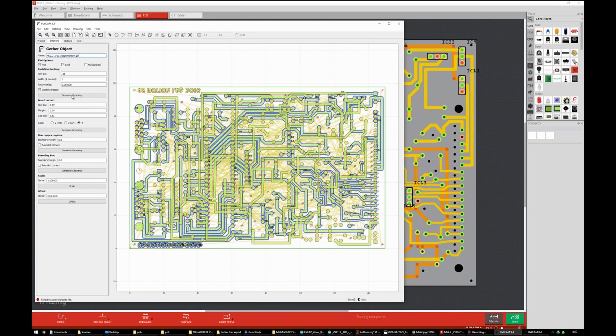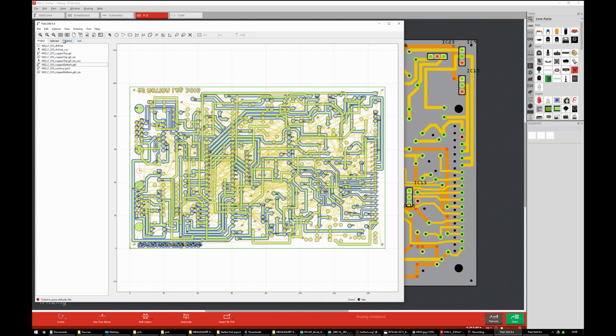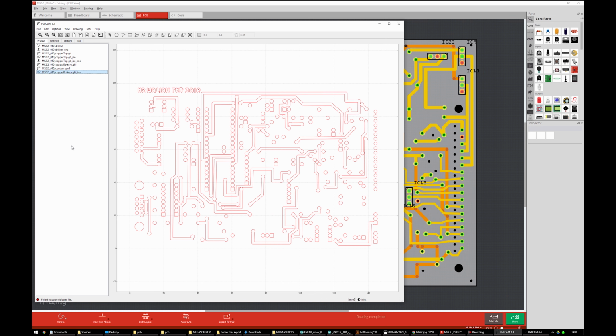Now in theory, all our tracks should be nicely separated. I'm just going to verify that by switching everything off, or as in how do we disable all plots but this one. That's what I need to do. So select the copper bottom ISO, disable all plots but this one. Just going to clean up our viewer here. Strips them down one by one, and here we go. Right. Oh, that's much better.